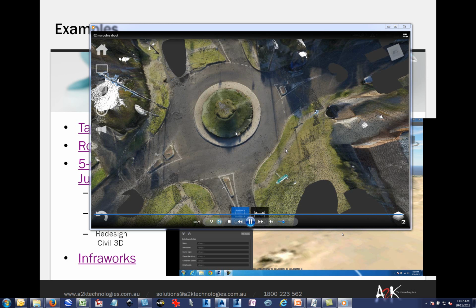So effectively you could freeze those afterwards using AutoCAD language. So I'll go here and hide that tree, which means that when I look from here, the tree isn't blocking my view. So that's a very quick view of what you would do with the desktop application, just to refine your mesh. You can also combine different surveys here, so you can use this to build up the model and then take it into your design engine and process it.